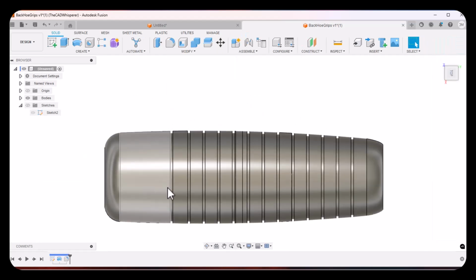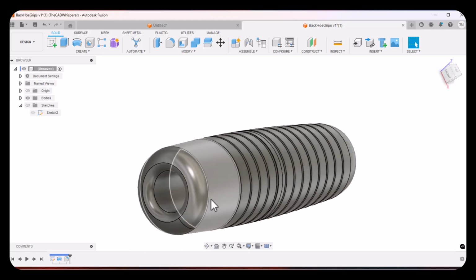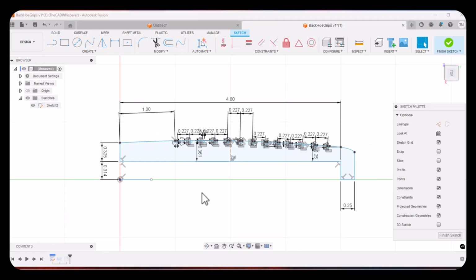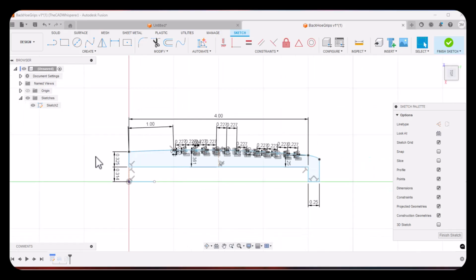Remember that this was a cylindrical object, so to measure the outside diameter with calipers, you would measure the diameter. To measure the hole, you would measure the inside diameter. You can't really measure the radius to the imaginary center of the hole. So it would make logical sense to dimension in the same way that you would measure that. Rather than giving the dimension as a radius, I would give it as a diameter. I would start out with a center line and then give that diametral dimension for the hole, the overall diametral dimension for the outside diameter, and so on.